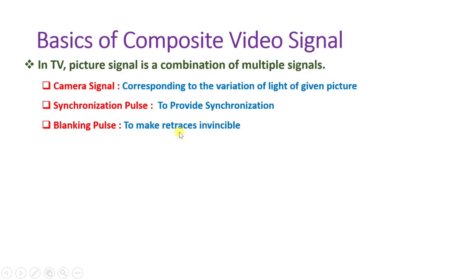Once the first line is displayed from left to right, a variety of camera signals with various amplitudes are obtained that correspond to the required image information. After horizontal tracking produces the desired camera signal for one line, the tracking beam is to the right of the image. Then a blanking pulse is inserted to restore the amplitude of the video signal up to black level so that the retrace can be cleared.